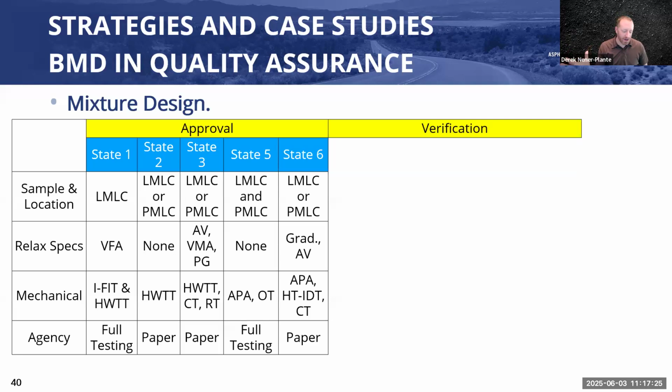And so, you could make anecdotal observations to say, well, all of our mixes pass and none of our mixes rut. I've heard that a bunch of times, but that's not real validation. You want that kind of direct point-to-point comparison as much as possible to have confidence in a threshold, whether it's mix design or acceptance, right? Either one, you need that confidence in order to really make balanced mix design work and move it forward.